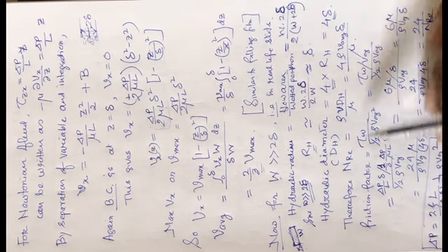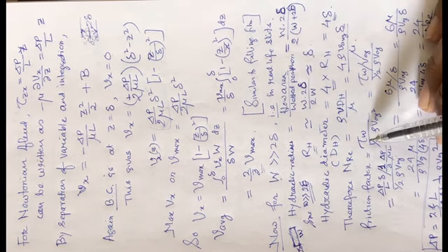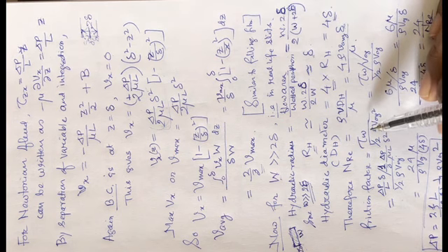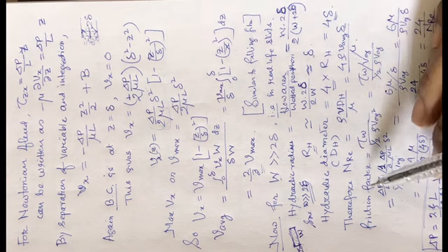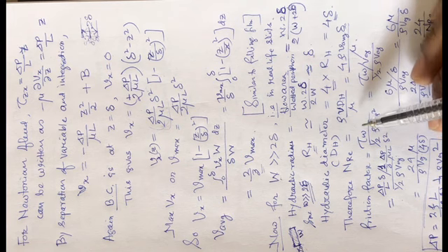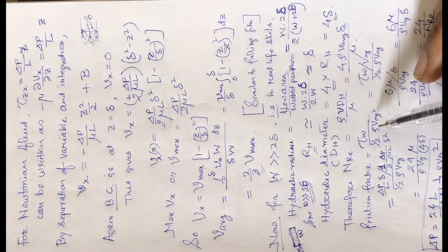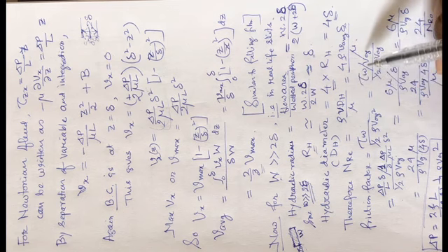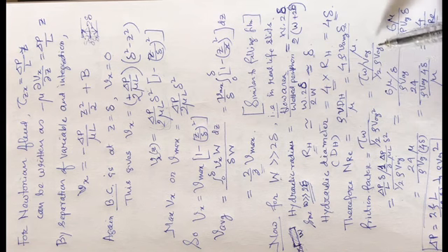Now the friction factor, you can recollect whatever we have done for the horizontal pipe flow. Friction factor is equal to wall shear divided by the kinetic energy term, that is, wall shear divided by half of rho into V average square.